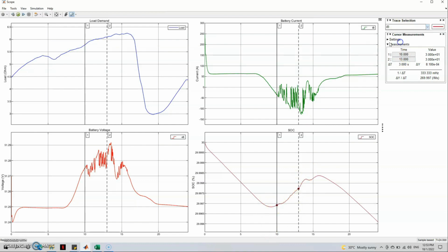So we can look at the battery current. The battery current is in negative value. We can look at it is negative 32.88 amps, while at 1 PM is negative 86.44 amps. Okay, we can look at the negative part of the battery. It is in the charging state for the battery.